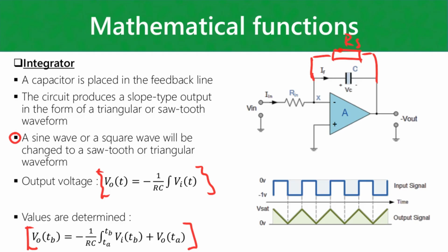Right, so you can get a DC offset from your input signal, or your output signal will generate a DC offset, and that will just get bigger and bigger as the frequency on your input gets lower and lower. So that's basically to limit the gain for DC and low frequency inputs.